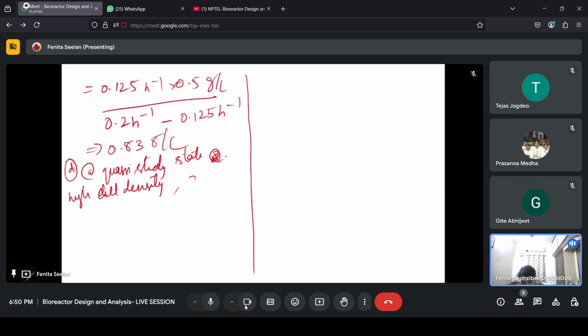It is assumed that the final substrate concentration will be lesser than the initial substrate concentration, and you also have to apply D approximately equal to mu. If you use this in the mass balance equation, it is the same formula we used in the previous question: X is equal to X naught plus Y X/S times S initial times flow rate times time for fed batch. This will give you the amount of cells produced at the quasi steady state condition.